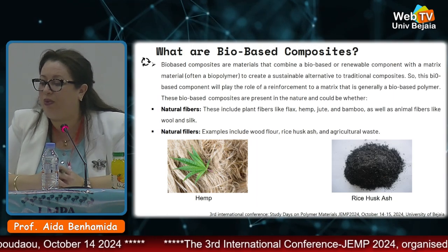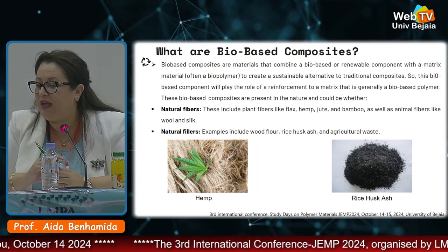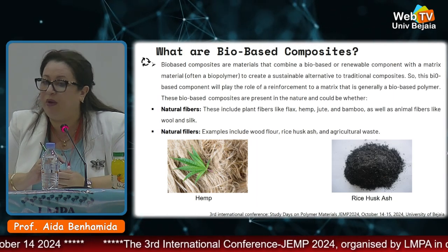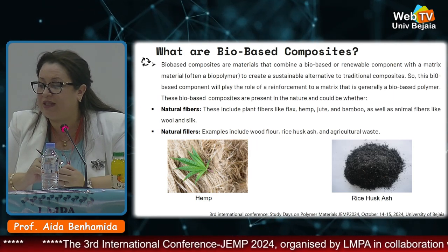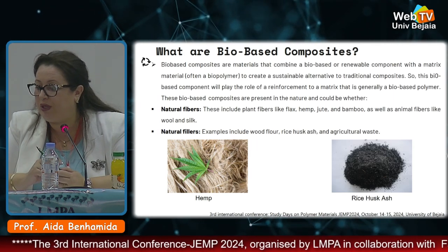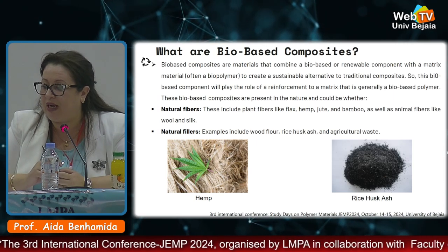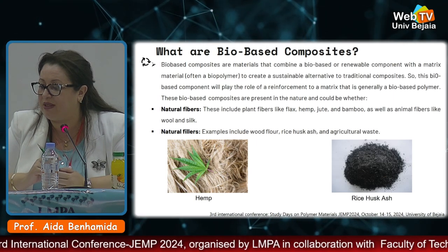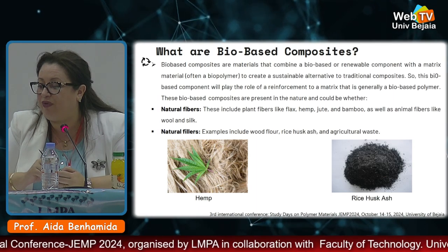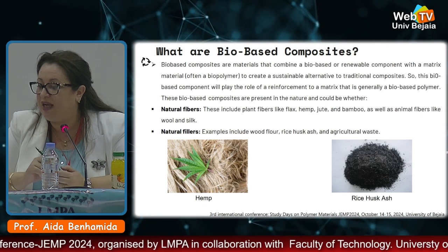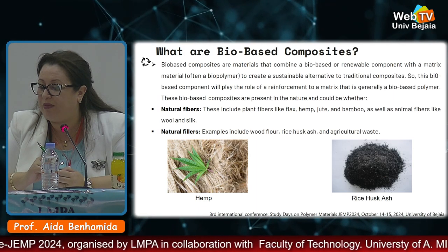What are now bio-based composites? They are materials that combine a bio-based or renewable component with a matrix material, often a biopolymer, to create a sustainable alternative to traditional composites. So, this bio-based component will play the role of a reinforcement to a matrix that is generally a bio-based polymer.